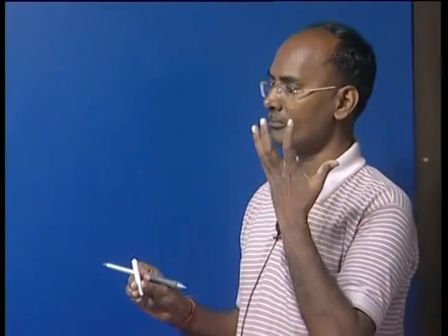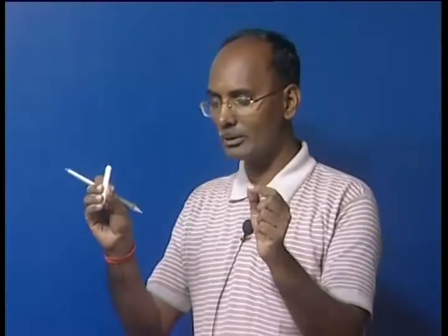So in this we analyzed, as I said, the different scenarios possible for commutation failure. How much time the commutation duration takes is a major concern. It can go for a longer period or a lesser period. All this depends upon your AC side conditions and DC side conditions.